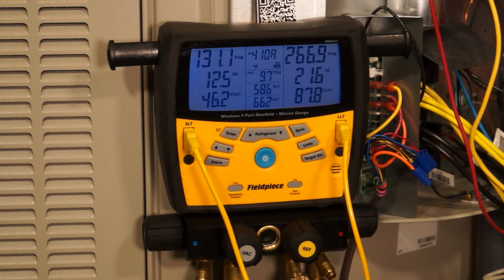Now, another thing you can keep in mind is when we were doing this test, I had to put the top of the unit back on, and that's mainly due to the fact that this is a good unit, and if I didn't put the lid back on with the condenser fan motor, the unit would go off on high head pressure. Now in the field, the symptoms that you would get for a bad reversing valve generally are going to be a suction pressure and a head pressure that are really close together. And you're really not going to be worried about going off on head pressure pretty quick.